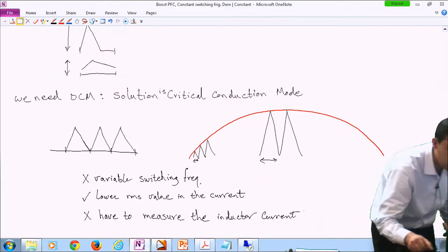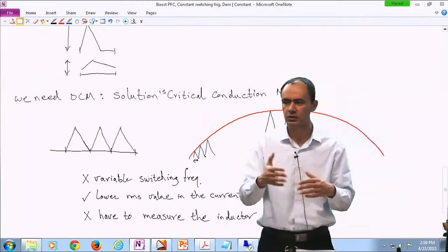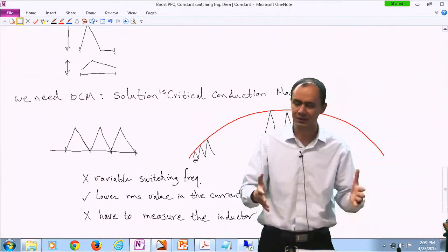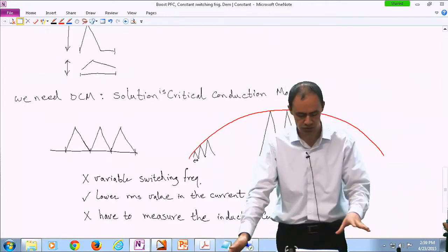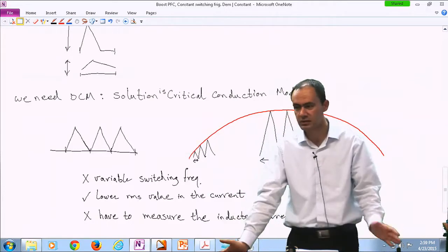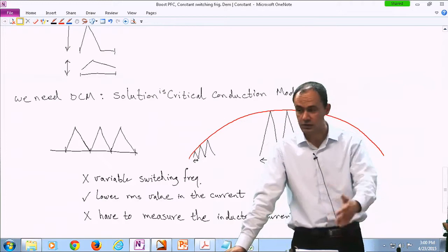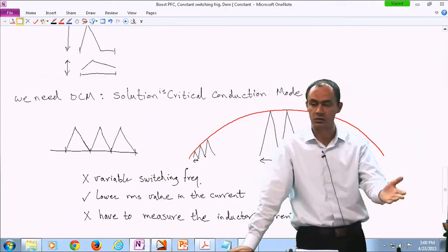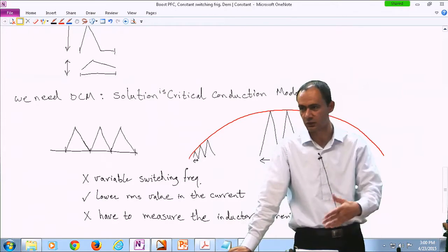Okay, I mean measurement, but honestly, all you care about is how close your inductor current is to zero. You don't really need the absolute value of the inductor current. Just is it getting close to zero or not? But still, that's kind of a measurement, so you have to kind of measure it. And yes, you're right. So once you do that, then the noise comes in. How much noise is riding on the signal that I'm reading? Is it accurate or is it not accurate?